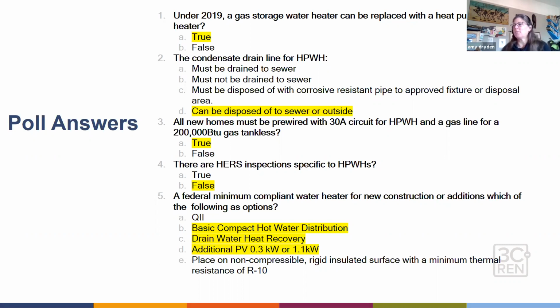Condensate drain line for heat pump water heater. Okay, it can be disposed of outside, to the sewer, into the sanitary system, whichever. It's just water, right? It's not a corrosive condensate as we see with our condensing furnaces or our condensing water heaters.